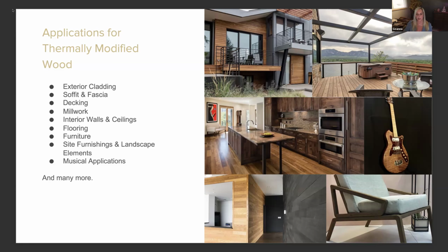Some of the European players will have a Thermo S versus Thermo D. And just so you know, Thermo D stands for durability. That's going to be all of your exterior building products where they're cooked to a much more extensive thermal modification, where they're cooking it for the 48 hours. Thermo S stands for stability, and that's going to be cooked for a lot less time. You'll use those applications for interior where they're much lighter in color, or they'll use those for sauna parts as well.